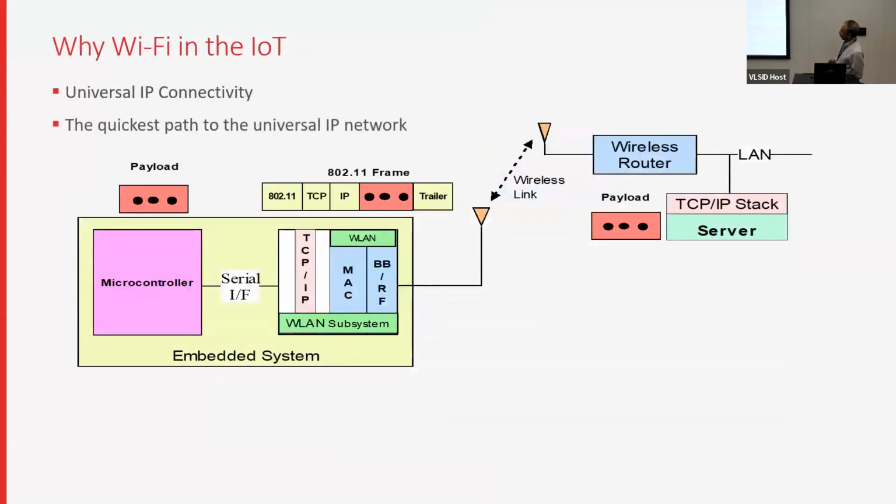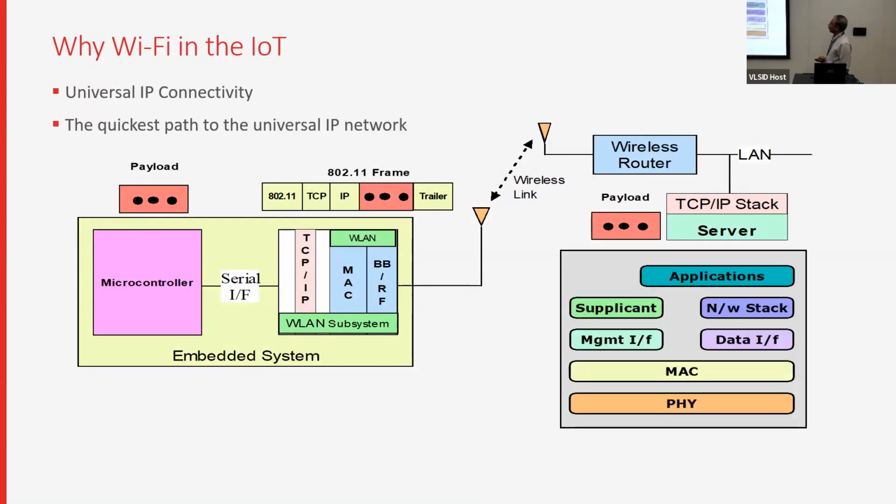The second thing is that Wi-Fi is defined to support IP at layer 3 and beyond. And the great thing about the IP layer is that you can encapsulate your data in IP, and then, to make it received robustly, you also have other protocols like TCP. On top of that, you can use anything else like MQTT and HTTP and HTTPS and so on. But the basic underlying protocol of all of them is IP. And everything has a unique IP address to which you're sending.